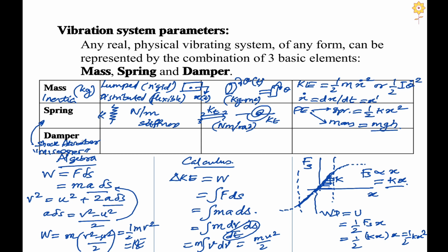The role of the damper is to dissipate the energy from the vibrating system into the surroundings. So there is a conversion of kinetic energy to thermal energy. There is fluid friction happening by virtue of shear effects within the fluid, and the heat created will be thrown out of the system to the surroundings through the cylinder walls. This is represented by a piston.